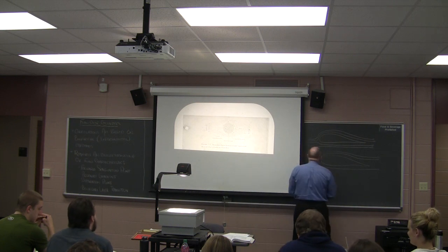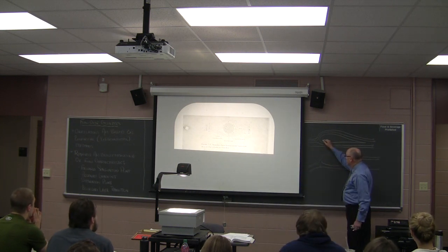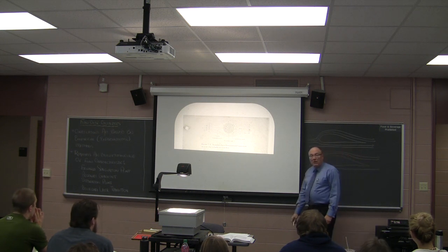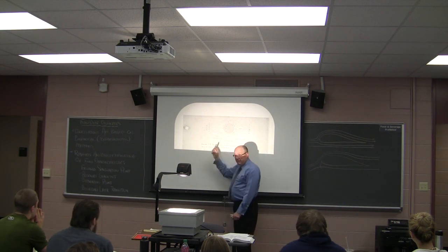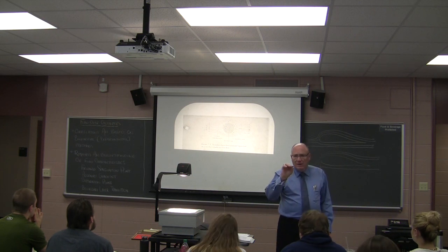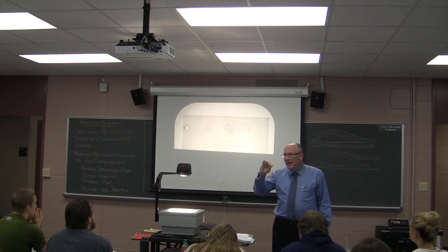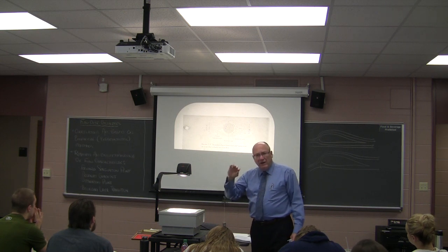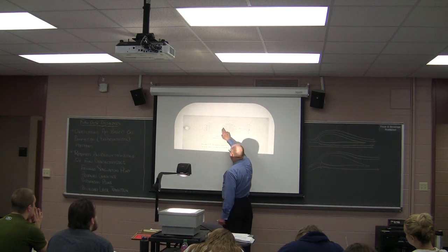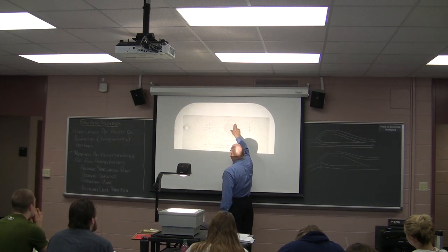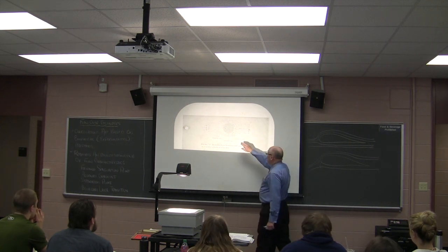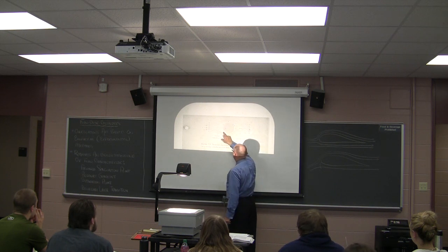but in any case, what do we have right here on an aircraft? On the airfoil, that is the stagnation point. That's the same thing as you have on a cylinder. What happens at the stagnation point? The air just kind of stays there. It's a little air that's right there. It's not moving. So there is this point right here. So as the air flows over, above and below, we are forming a boundary layer on the surface.